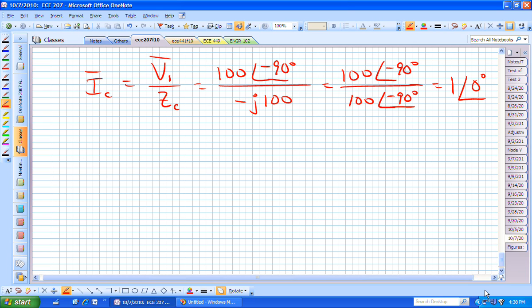Question? All in the real direction? By 0 degrees, all of these angles, we are referring to the positive real axis. The voltage we were given started at 0 degrees, and now we're finding everything relative to that particular voltage reference phase. I was now the current going into that node that we solved for.